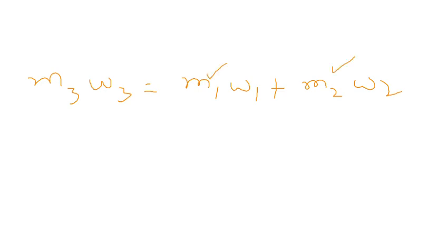Now the second part is you are required to find the moisture, that is specific humidity at 3. So again we write down the moisture balance. And now what is the moisture balance? M3 omega 3 is equal to M1 omega 1 plus M2 omega 2. We have found out the values of M1 and M2. We also know that M3 is M1 plus M2, right?